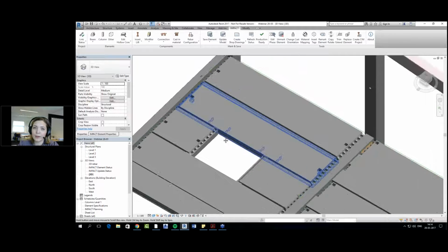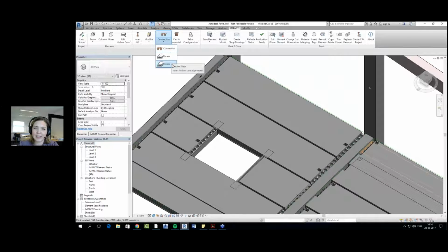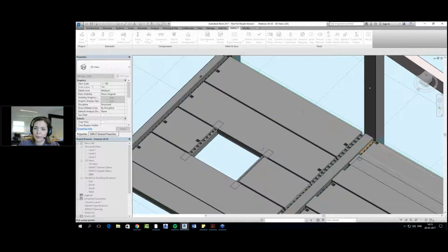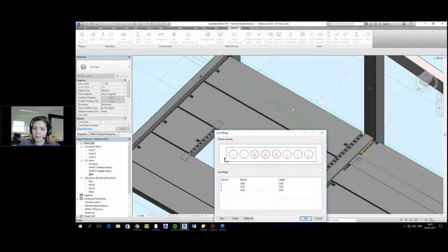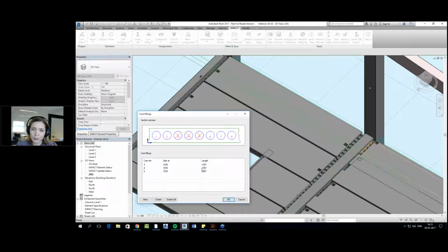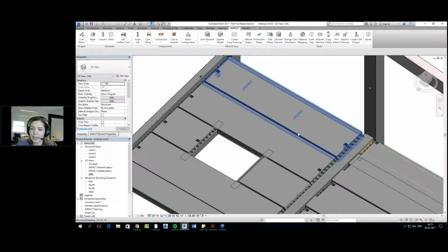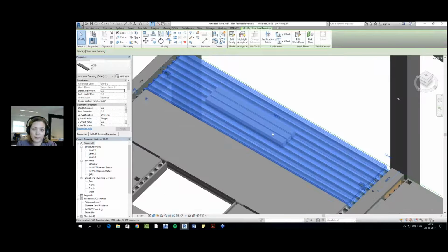As we have made some recesses and recess edge, you can also add recess and recess edge that will come from the settings we have just made. But we can also make some core filling for other slabs. So let's say we want to have a core filling somewhere here, as we have this line made. So that means we will have cores filled in 3, 4, and 5th cores. Dimensions come from the standards we have in geometry from the settings. And then I say OK. If I click on this element, you can see that the cores are filled.